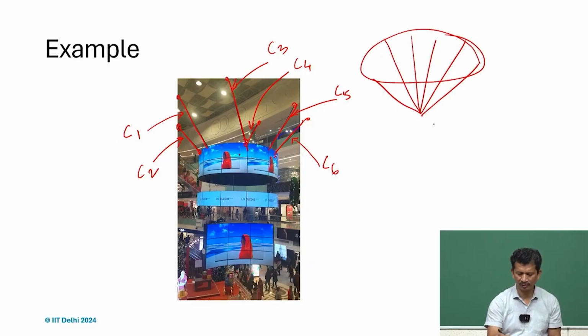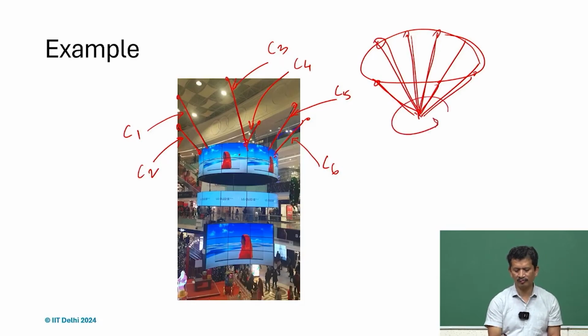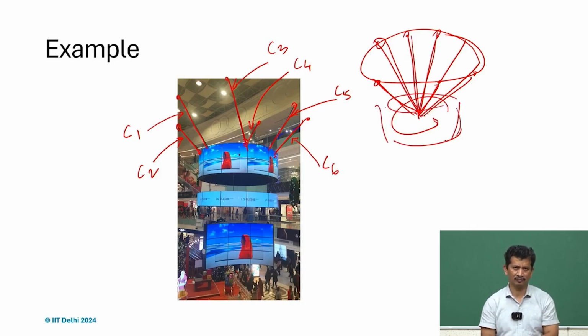So, what happens if all of them are intersecting at one point, and suppose it's placed here, 3, 4, 5, 6. If you try to rotate the object, you cannot constrain that rotation. So, it's an over constrained design. It means it's a no. So, it should be done differently, and I think it was nicely done.